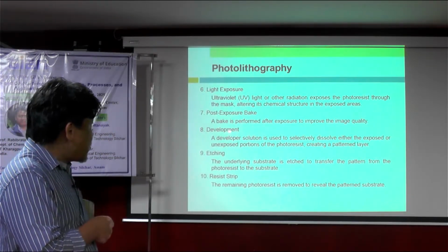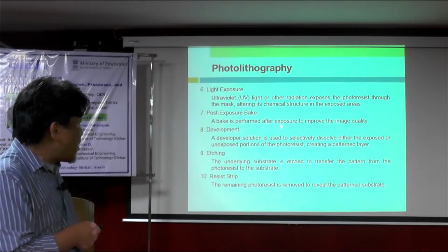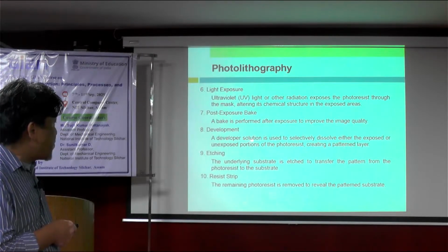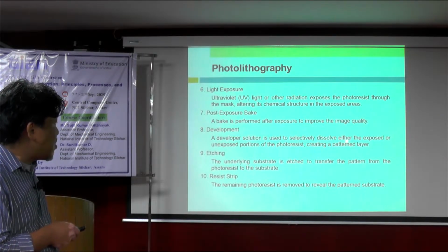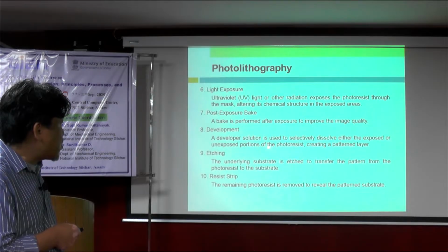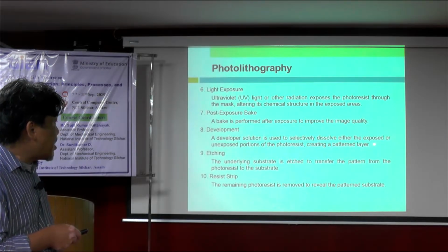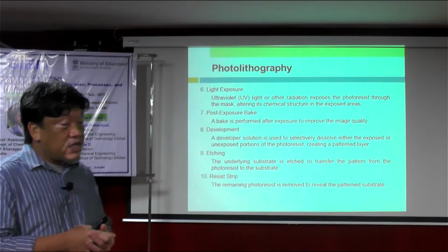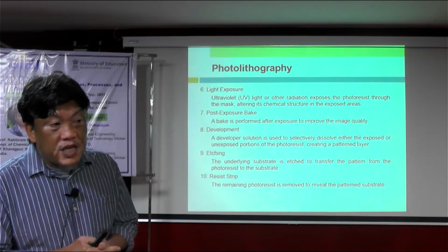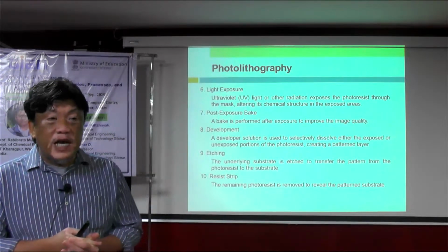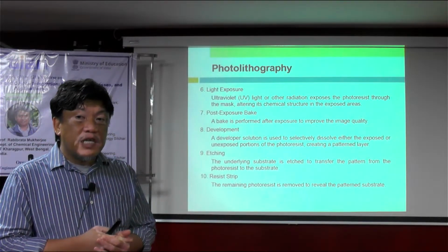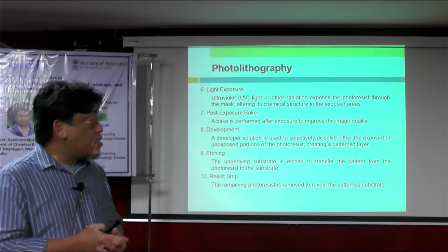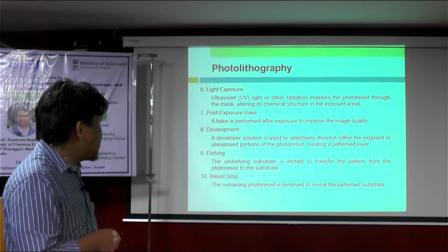And post-exposure bake: a bake is performed after exposure to improve the image quality. And development: a developer solution is used to selectively dissolve either the exposed or unexposed portion of the photoresist, creating a pattern layer. So here it depends on your photoresist. If it's a positive, you want to remove the exposed part. If it's a negative, you want to remove the unexposed part of the photoresist. So this is the development process of the pattern.